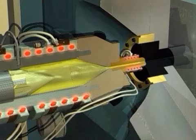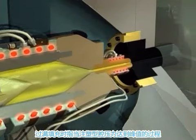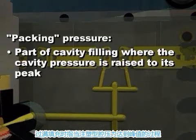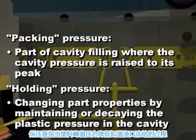A word about terminology. We use the terms packing and holding pressures to describe different phases in the molding cycle. We use packing pressure to describe the part of cavity filling where the cavity pressure is raised to its peak. We use the term holding pressure to describe how part properties are manipulated by maintaining or decaying the plastic pressure in the cavity until the gates freeze.